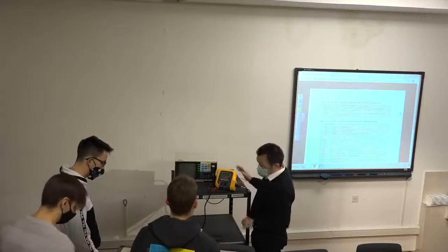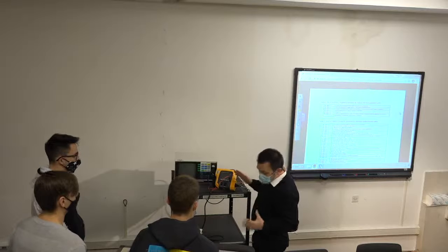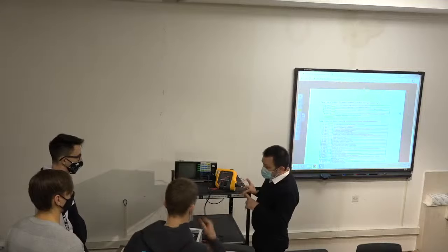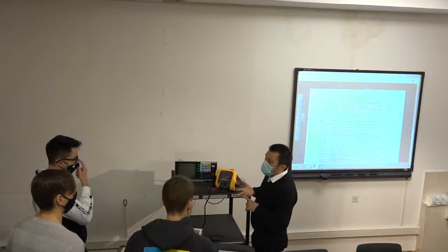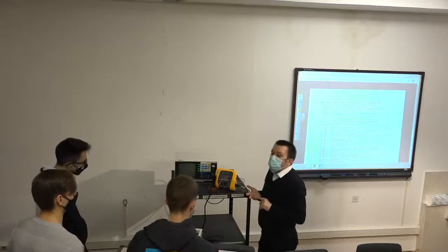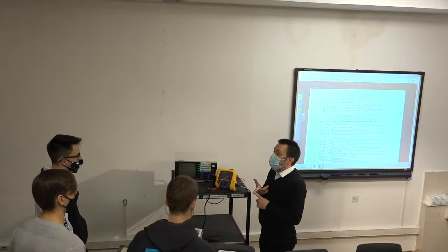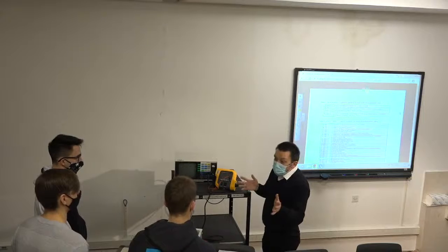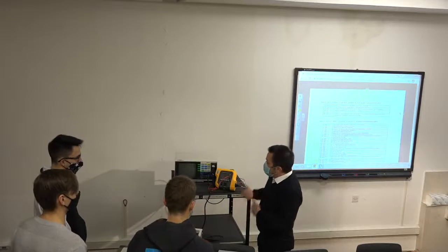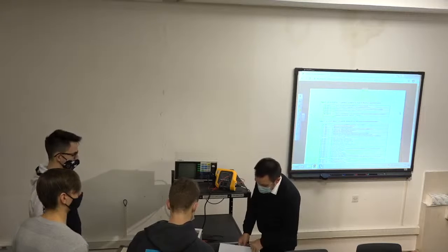So this device is checking mainly some resistances, currents, primarily the leakage currents, and voltages between the parts, mainly where there should be no current or no voltage, or where the actual resistance should either be short or open, because that's the whole idea. But we are not living in an ideal world, so we have to check the devices in such an environment.